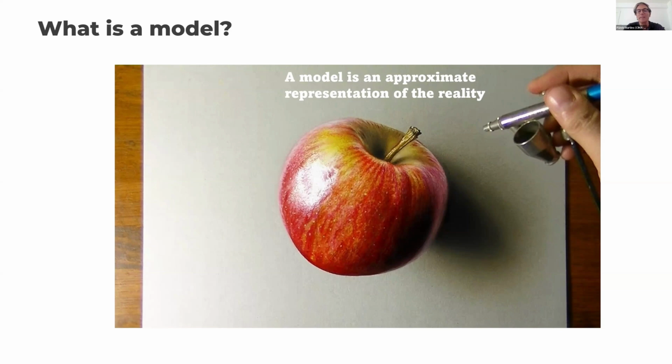So the same in a mathematical model. For example, if you decide to simulate an estuary with a 2D model, you don't have differences in velocity from the surface to the bottom of the estuary. So there is no sense searching for stratification or a salt edge in the estuary using that kind of model, because the model doesn't show it.